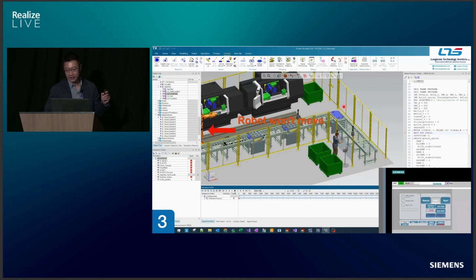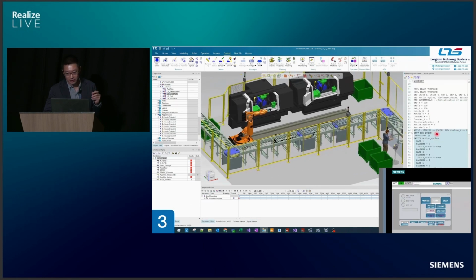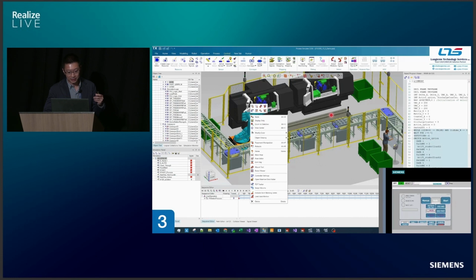What's going on, right? If you pay attention to the right side of this screen, you see there's a small yellow arrow. That is where your robot program stopped. So we can see what's going on. The robot is waiting for input signal number 4. For some reason, the robot doesn't receive the signal, or the signal status doesn't change.